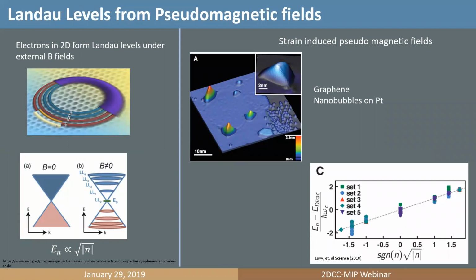How much strain can you apply to graphene before crack propagation begins as a defect? I think it's about 20%. About 20% is the number. People have taken a graphene sheet and punctured a hole with the AFM tip, and by measuring how much force you need, they can calculate it's about 20%.